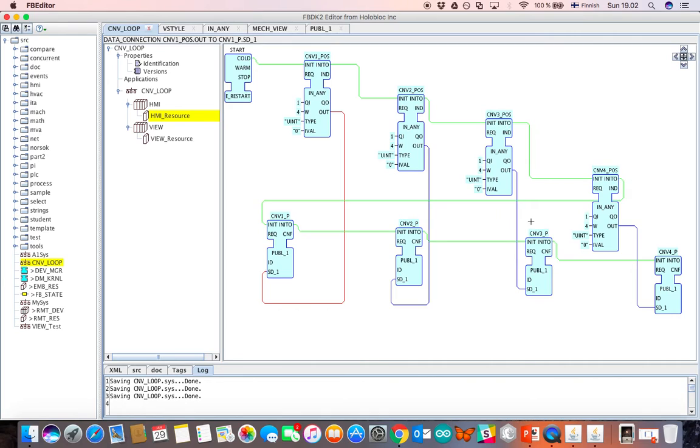I have initialized all the blocks with the init inputs outputs, but I forgot to provide the request event, and this request should be coming from the indication event. So we have connected initialization data, but I have forgotten to connect events. So the indication of the block comes to the request of each of the corresponding blocks. Let me try to adjust it to see better.